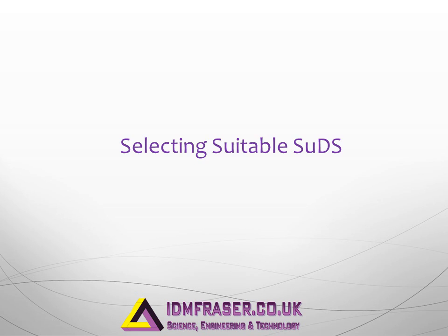Selecting a suitable SuDS. SuDS can take the form of both procedures and devices. Procedures can include safe disposal of pollutants, detailed instructions on unloading oils and chemicals in a factory, asking dog owners to collect their pets' feces for safe disposal. But irrespective of the type of development, residential or industrial, prevention should always be considered first. Containment should be considered on industrial sites to prevent chemicals or hydrocarbons polluting the environment.